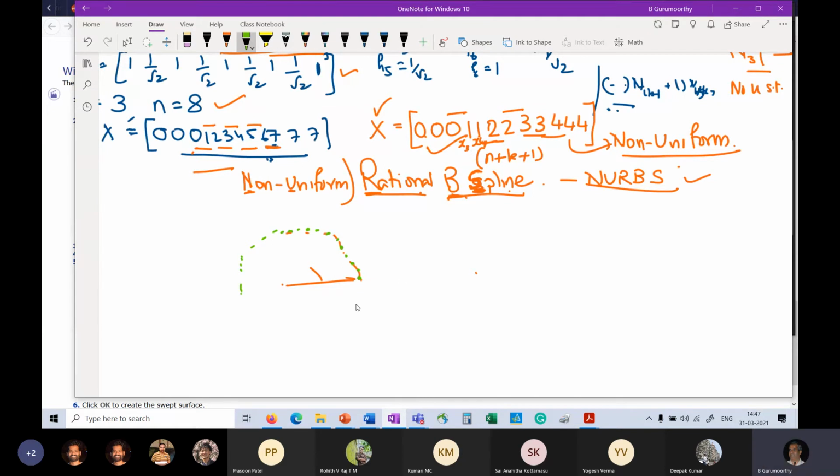And actually, that is the input that we have not studied at all, which is that my curve may not be a circle, it may be some arbitrary curve, but it is defined as a series of points that lie on it. So now I'm not trying to define the curve. I'm giving you points that lie on the curve, and I'm asking that you give me, the CAD system, a representation for a curve. So this is a problem that is variously known as curve fitting or curve interpolation.